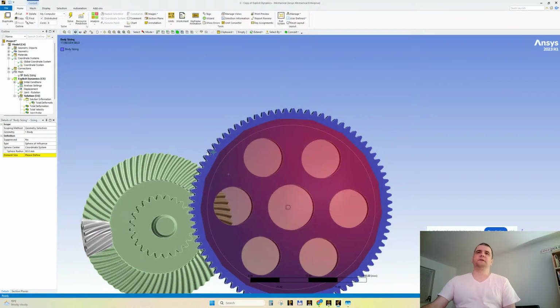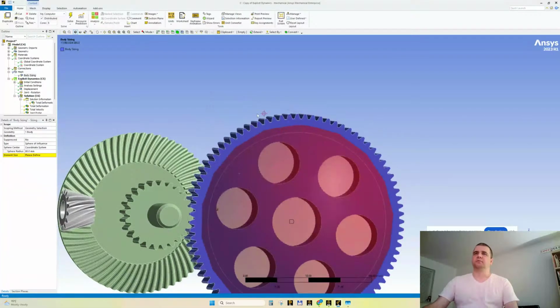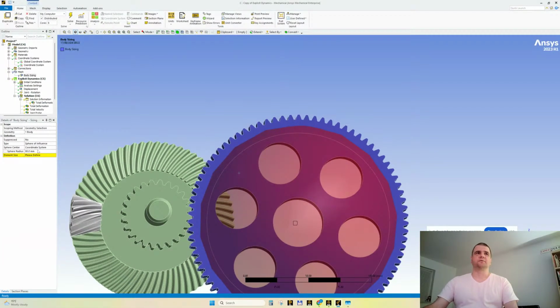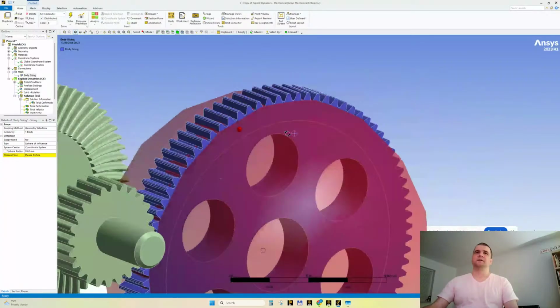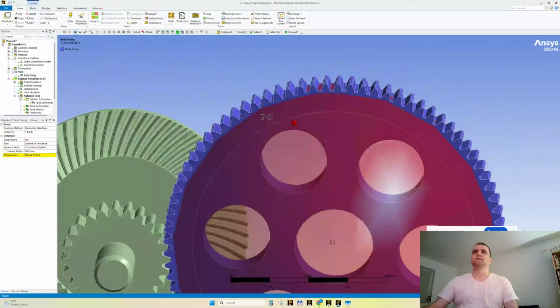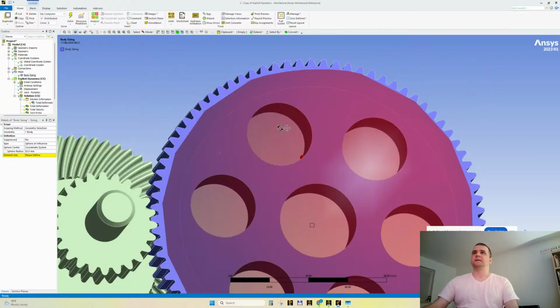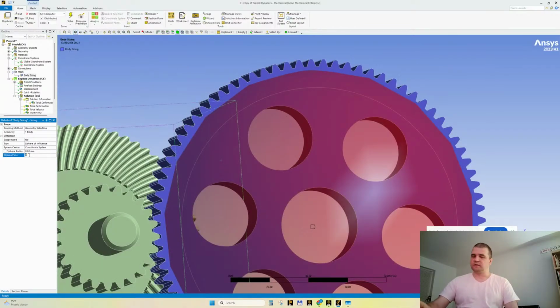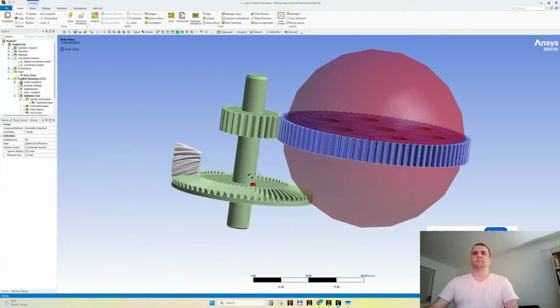Why? Because we need only the teeth to be fine as mesh, the crown, let's say, but not inside. Inside we need to be as coarse as possible. 85, is it better? Yeah, kind of, but it goes here, so let's make it a little smaller. Maybe 83. All right, so this portion I would like it to be coarse, I mean 5.5, for example.